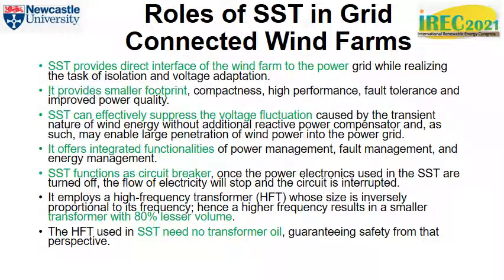Solid-state transformer can effectively suppress the voltage fluctuation caused by transient nature of wind energy without additional reactive power compensators, and as such may enable large penetration of wind power into the grid without any problem. It offers integrated functionalities of power management, fault management, and energy management.